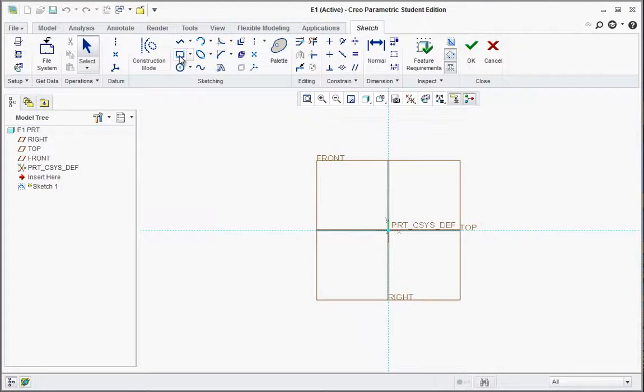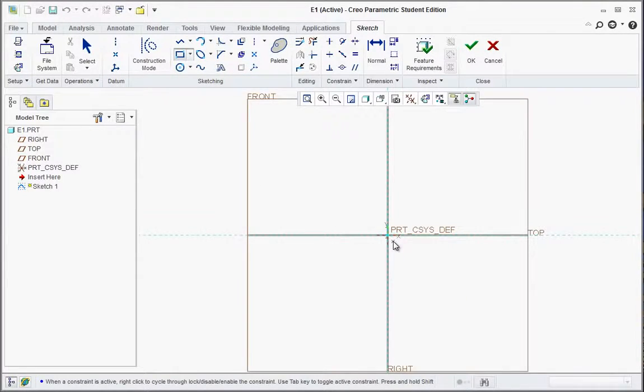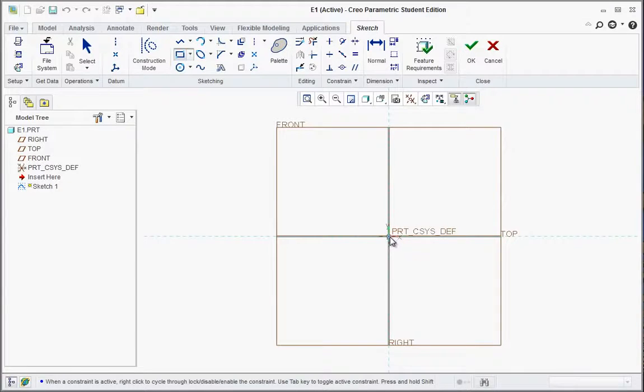Now, I'm going to go ahead and select the Corner Rectangle tool. Typically, when you see a little arrow to the right of any tool, you'll see that there are several other options. We just want Corner Rectangle. And glide up to the center, and you can zoom in and out with your middle scroll. If you scroll in and out, you can zoom up to that. Click and drag out